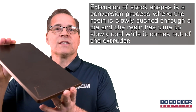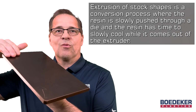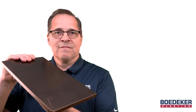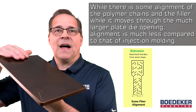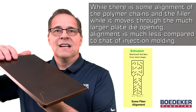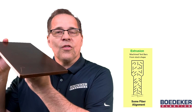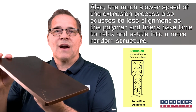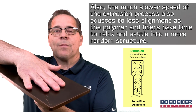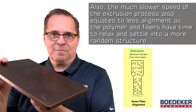Extrusion of stock shapes is a conversion process where the resin is slowly pushed through a die, and the resin has time to slowly cool while it comes out of the extruder. While there is some alignment of the polymer chains in the filler while it moves through the much larger plate die opening, alignment is much less compared to that of injection molding. Also, the much slower speed of the extrusion process also equates to less alignment as the polymer and fibers have time to relax and settle into a more random structure.